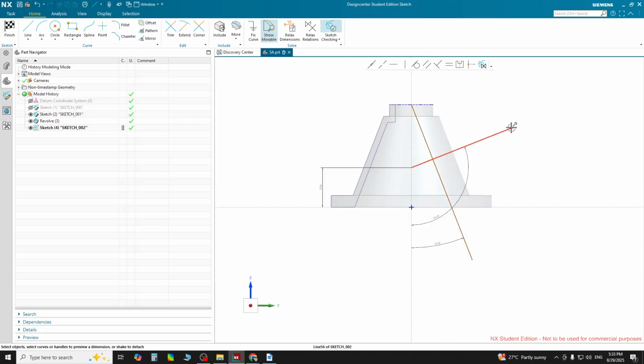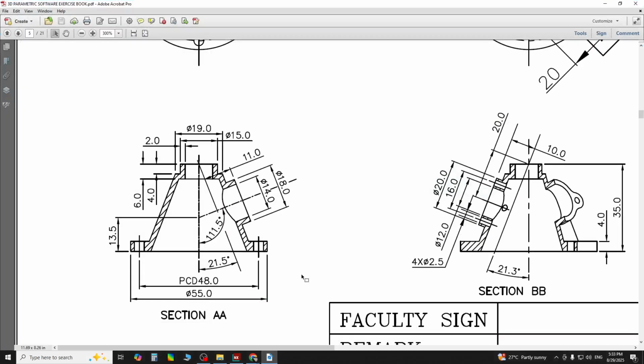Now one thing is remaining here, that is the end point, which is very important. So end point, we see here this line, to this portion, to this portion, you see this line. So where this sketch will be made, the sketch will be prepared to that line, that plane. From the sketch plane to that line, the parallel distance will be 11.